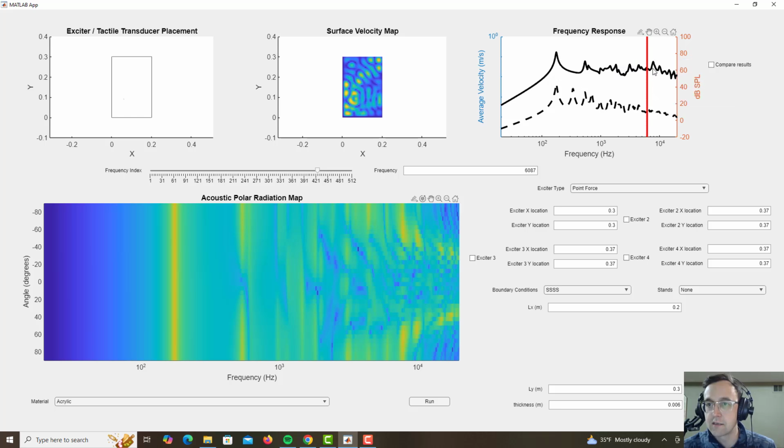But even though this is just the average, that peak tends to be more towards the beaming towards the edges. And then above that, usually the average acoustic response goes down quite a bit. So coincidence frequency is usually a good thing to try to push higher. And by making panels thinner, you can push that higher.